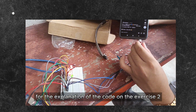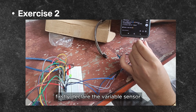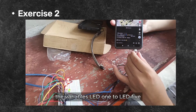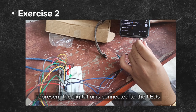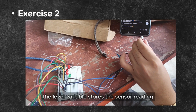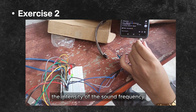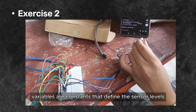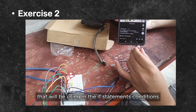For the explanation of the code on the exercise 2, firstly, declare the variable sensor to represent the analog pin that reads input from the sensor. The variables LED1 to LED5 represent the digital pins connected to the LEDs that we will be using. The level variable stores the sensor reading, which could represent the intensity of the sound frequency. The different threshold variables are constants that define the sensor levels that we'll be using in the if statement's conditions.